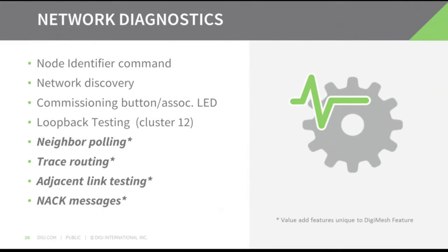One of them is trace routing. In DigiMesh, you're able to send a packet with a trace route flag. This will then send back to your transmitting module the route that was used to traverse the network. So really nice for diagnostic and troubleshooting scenarios.